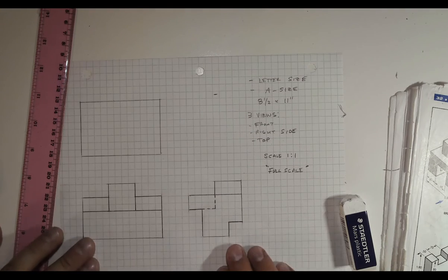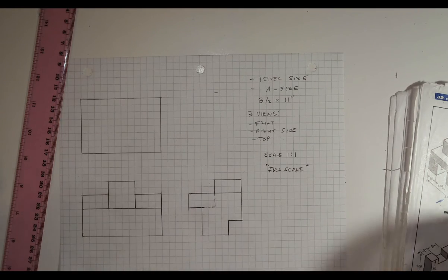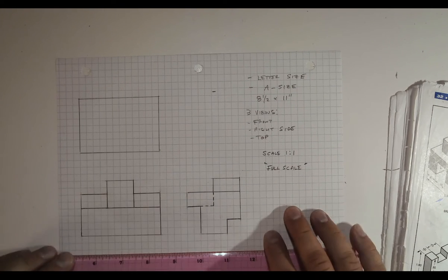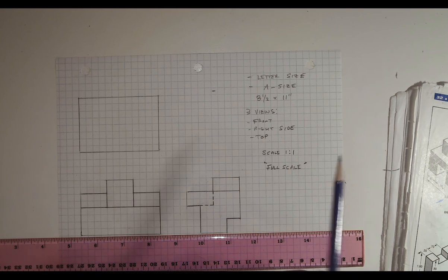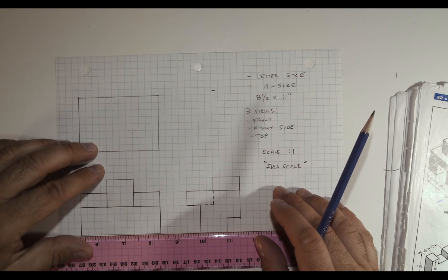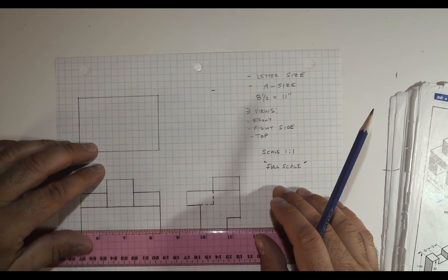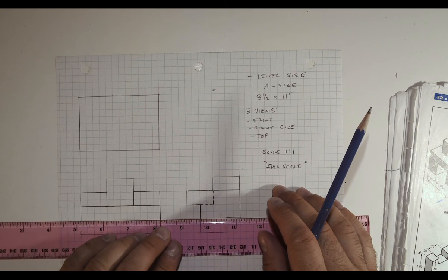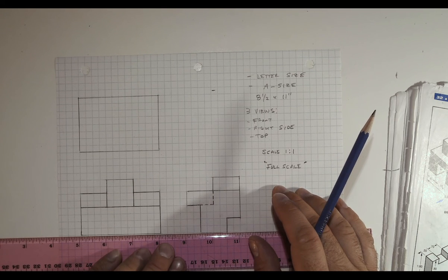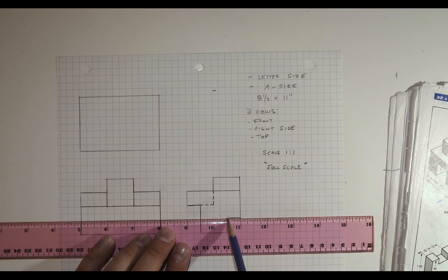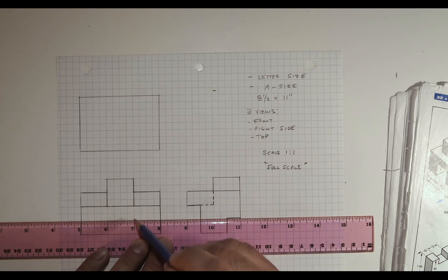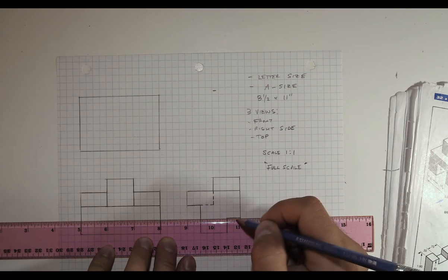So another thing I want to show you is how to use your ruler to help you error proof. So what you should do is use your ruler to align edges from one view to another to see if you're missing anything. So if I go along here and I run in with my ruler to this edge, which also represents a surface along the rear of the part, I can clearly see here now that I am missing that feature in the front view. This should be shown as a hidden line.